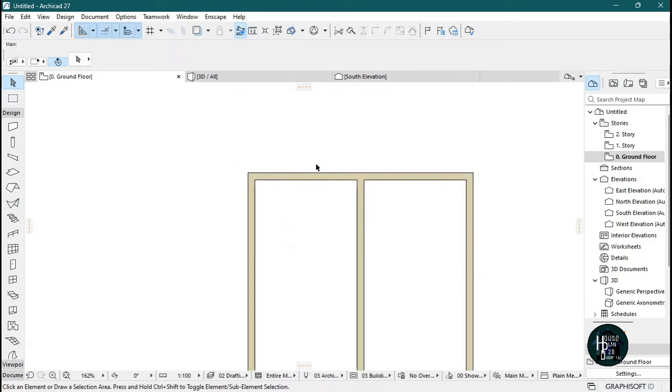Okay, now the next thing I want us to do is the distance from here. Initially we said it's going to be 6,750. Okay, so you will click M on your keyboard and pick a distance from here. So we're supposed to be having 6,750, but we're having 7,291. So the next thing I want us to do is we want to try and reduce this.